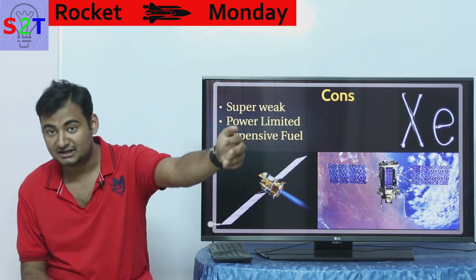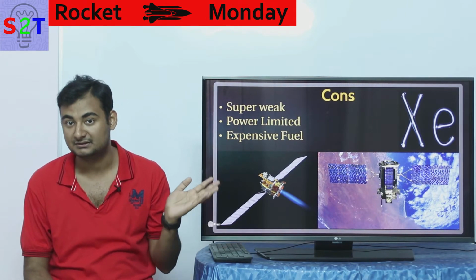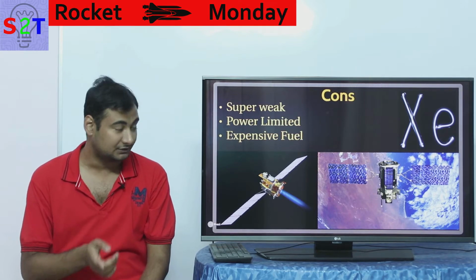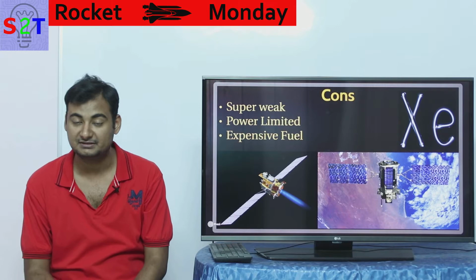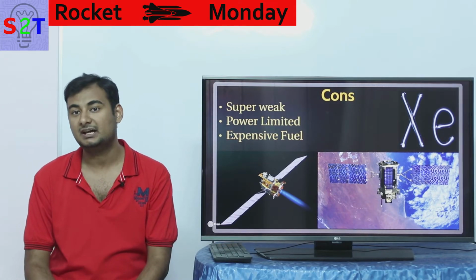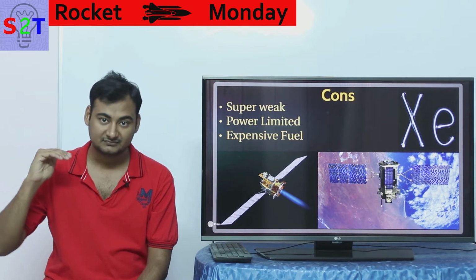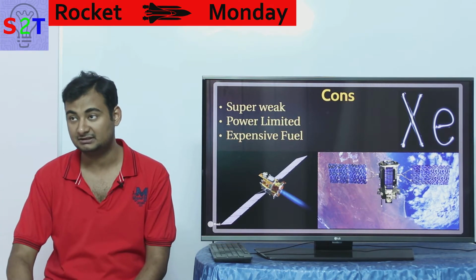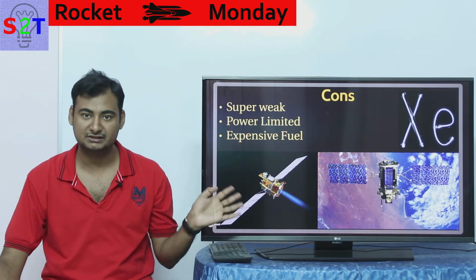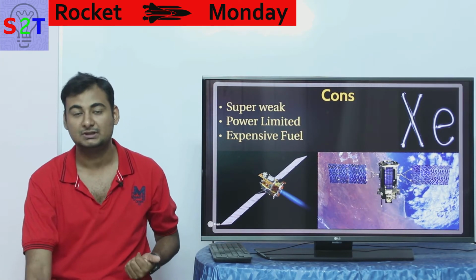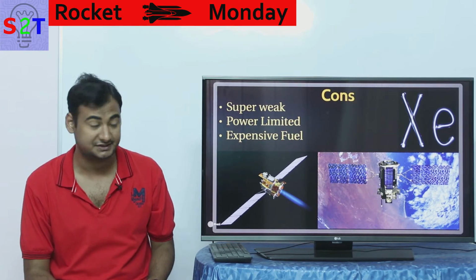Now while it's going to Mars, it will lose power, and consequently your rocket engine will also lose power, because ions need electricity to work. So for this reason they are very power limited. All the Dawn mission and Deep Space missions that use ion engines are generally in very elliptical orbits. Sometimes they only use this when they are facing the sun, and not to mention that you can't reliably use these to go to Pluto, and that's why everything we send to Pluto generally has RTGs.